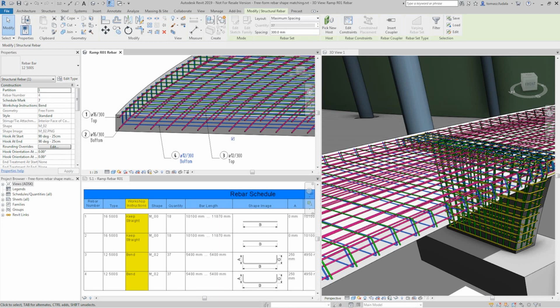So in this case, I'm actually producing a bar bending schedule for the rebar, which obviously takes my design to a whole other level. We don't need to go to that level, but you have the possibility of going down that direction. And sometimes this can give you better insight into your design, because what you do conceptually in 2D might physically not actually work in 3D.